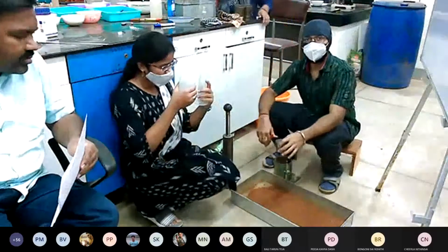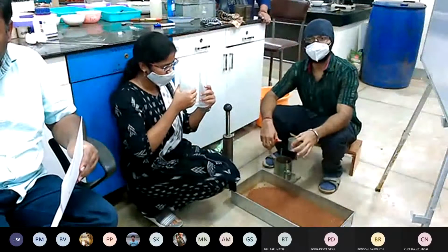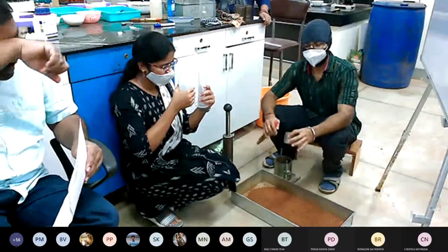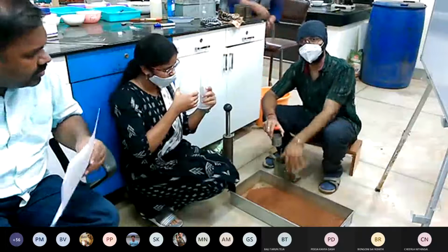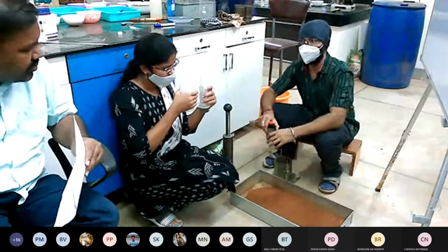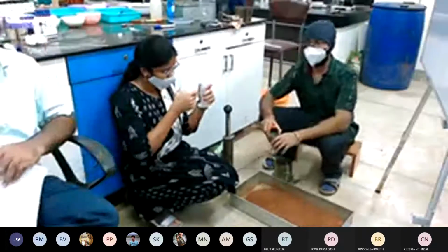We have taken 3 kilograms of dry soil. So we'll start at 2%. 2% of 3 kilogram will be 60 ml or 60 gram of water.